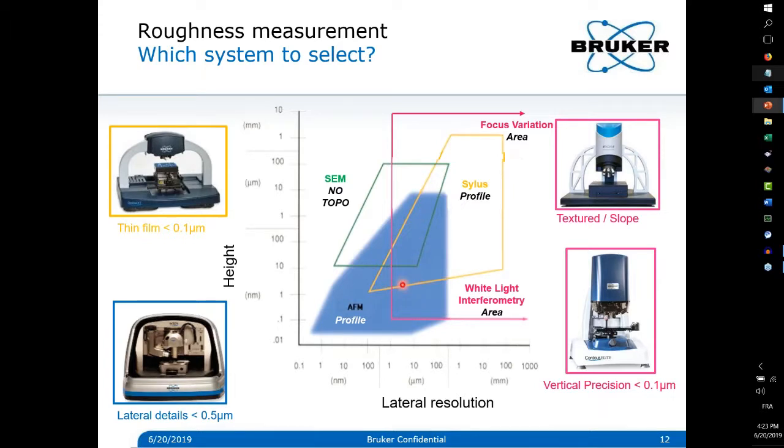But the main reasons why it is still in use are twofold. The first one is we can easily break, let's say, the standard light diffraction limit of 0.5 microns by using sub-micron styli, such as 0.2 microns, and see details around 0.2 microns without switching to atomic force microscopy. And the second point is this technique has no issue with multiple thin transparent layers.